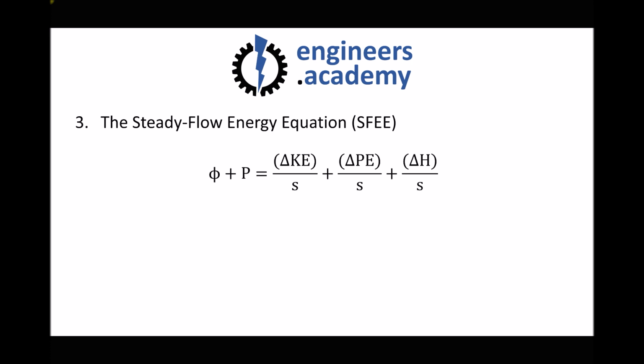Another important takeaway from this video is, depending on the scenario or depending on the system, we can actually begin to cancel some of these terms out. So I recommend always starting with the full steady flow energy equation and then analysing the system in order to see which terms are no longer relevant in the formula. And I'll give you an example of how to do this.